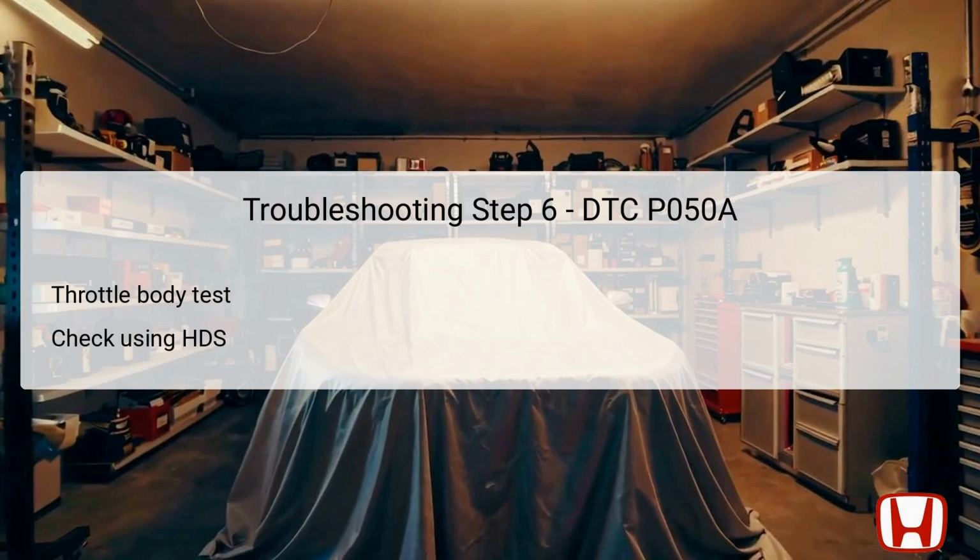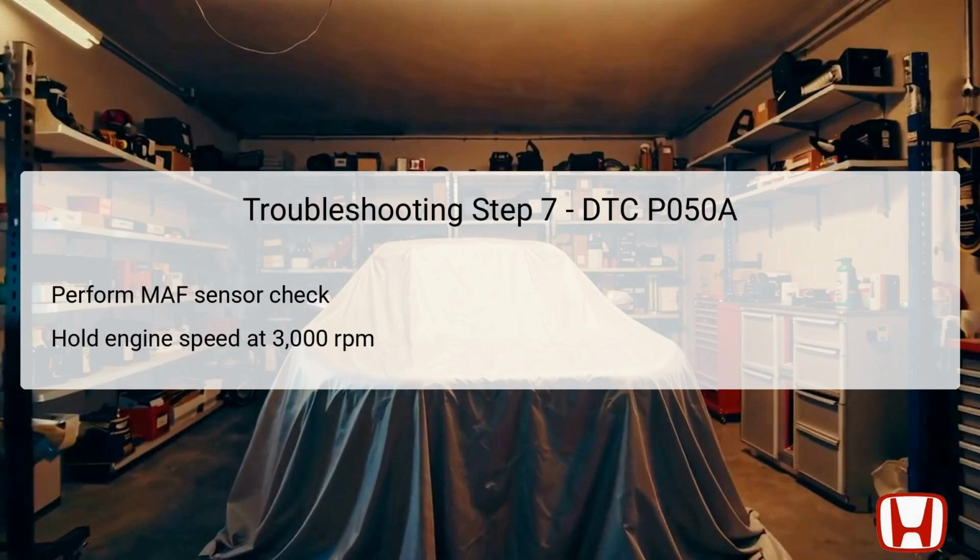Take particular care during this step, as a faulty throttle valve can significantly affect the air-fuel mixture and idle stability, which are essential during cold engine operation. Next, you will check the mass airflow (MAF) sensor performance.